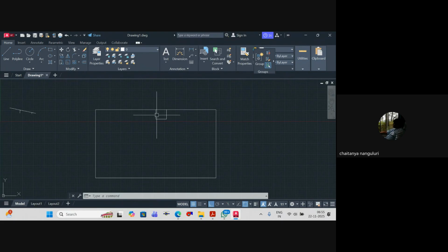So when you have the beam height as 400 mm, then you consider this space is different, this space is different. But this rule generally people wouldn't follow, because anyway you've got a false ceiling to take care of it. That's the reason. Am I clear? But for exposed slabs, you'll take this particular one.